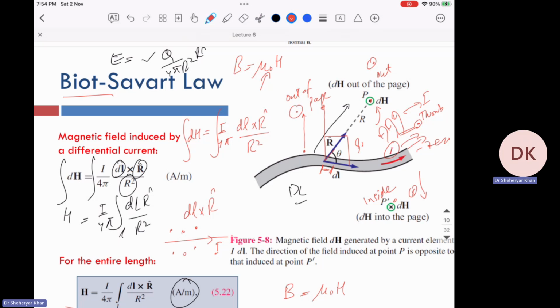Actually, you have a positive pole here, the positive point of the battery, and the current flows from here, right? And then it comes here and then comes here, right? But there's a magnet at the bottom, so the magnet also produces a constant magnetic field. And because one end is going down, another is going up, it feels again the same torque that we have discussed. One is pushing this way, another is pushing this way, and then it moves here, and the magnetic field is on the three sides, right? All the sides uniform, so it starts spinning and spinning.